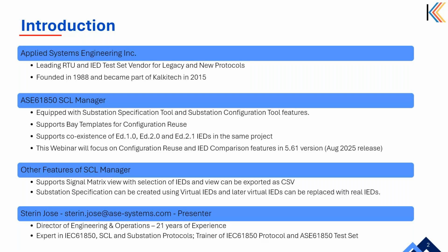ASC's 61850 SCL Manager is a substation configuration tool. This tool allows you to design and configure 61850 solutions from the top down, bottom up using vendor files and inputs. And we support the use of Bay templates, which will allow for configuration and design and gives you the ability to rapidly reapply that configuration as you scale up.